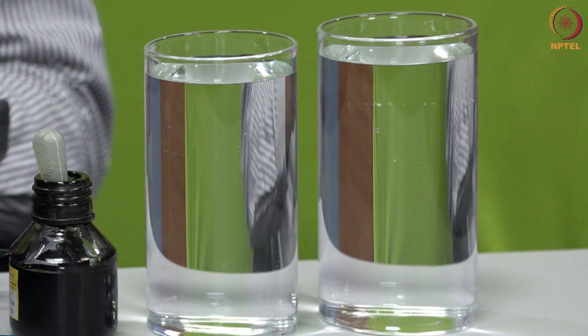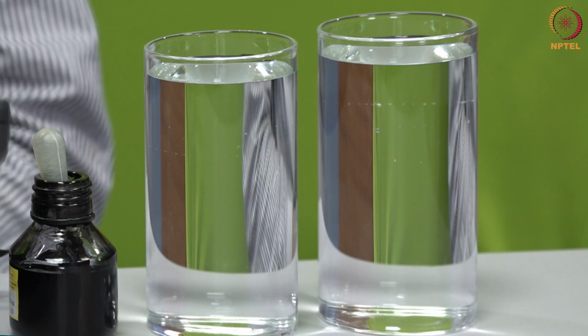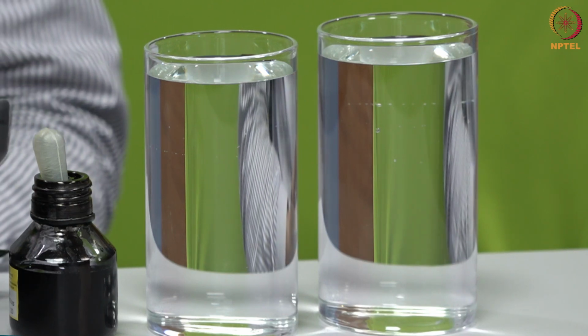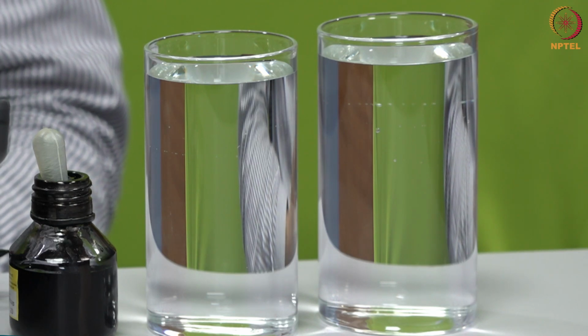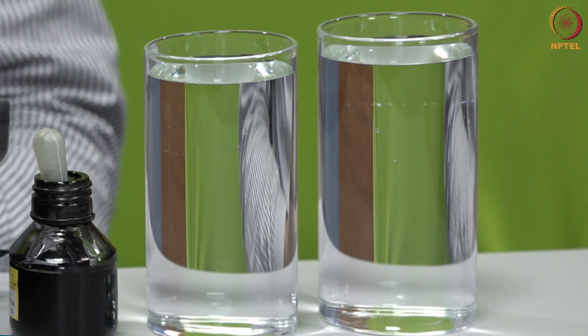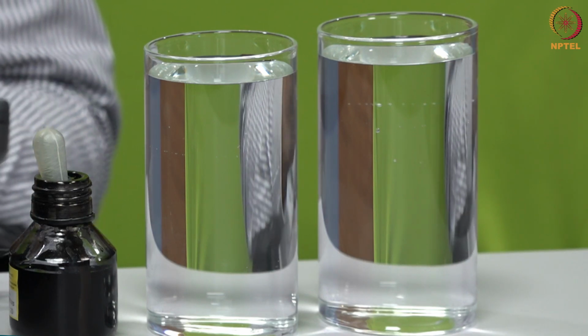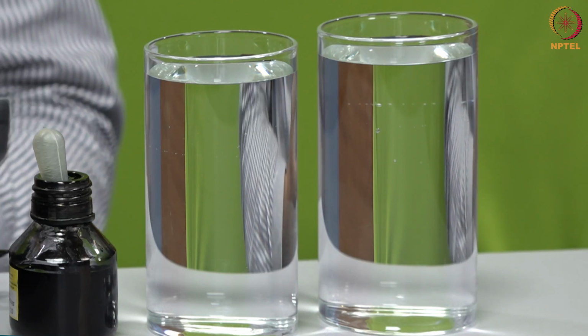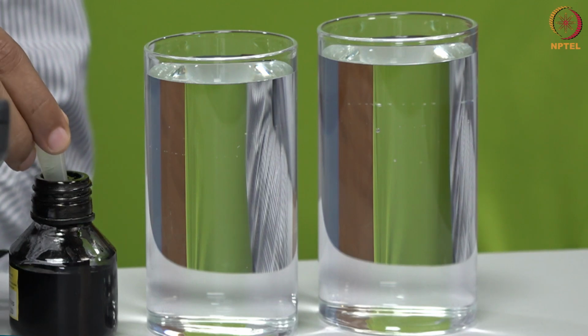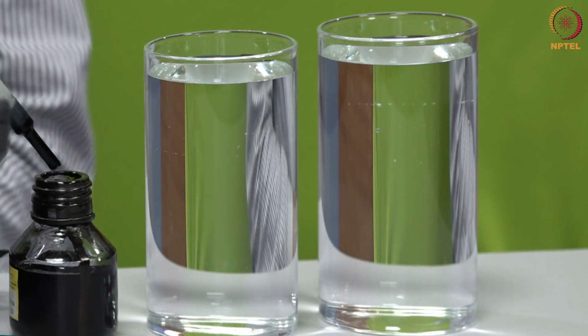So for example, one possibility is that as soon as I drop this black dye, it can all go straight down like a spaghetti, showing no oscillations, and that means perhaps it is developing a laminar flow, right? Or it can go completely random, all going in a random fashion, indicating that it can be turbulent. So let's see what happens if I drop 2 droplets, one in each, and we will observe how it develops in both of them, right?